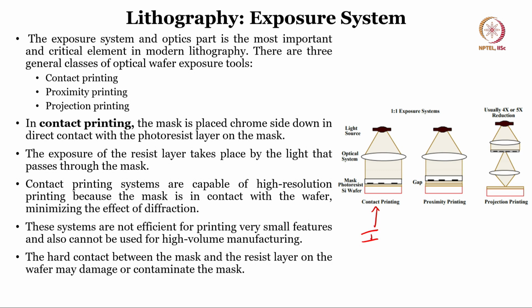But the hard contact between the mask and the resist layer may damage or contaminate the mask. So, these are the advantages and limitations. The advantage is that you can have a better resolution; the disadvantages are that it cannot be used for high volume manufacturing and can contaminate the mask. Let us go to the second one, which is proximity printing.